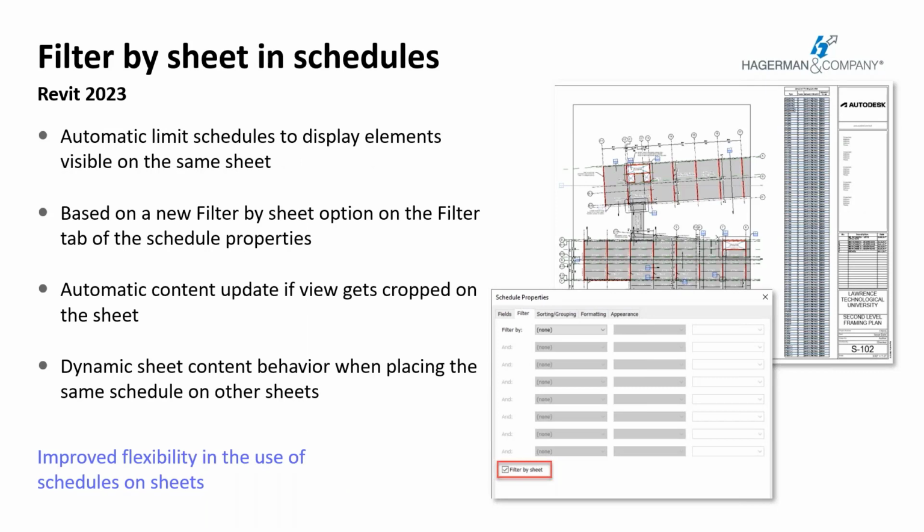So this could definitely be my favorite new feature. In Revit, a schedule is used to display a customized list of elements and their parameters that exist within your project. Schedules are powerful tools in that they are live, non-graphical views of a project. As such, they automatically update as elements are added, removed, or modified from the project. Schedules can be dragged and dropped onto sheets, much like any other view.